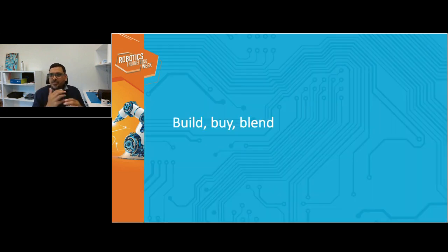So that was just the first two. We looked at the inverse kinematics problem. We did the translation lookup table to solve that problem. And then you had the compliance and the linkage issues. You were able to compensate for it by adding feed-forward compensation tables in the controller.